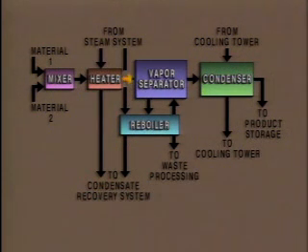From the heater, the heated liquid flows to a vapor separator. In the vapor separator, some of the components of the hot mixture flash to vapor. The other components remain in the liquid state. This flow path represents liquid in the bottom of the separator that is sent to a reboiler. In the reboiler, part of the liquid is vaporized. The vapor from the reboiler is returned to the vapor separator. The waste product that's not vaporized in the reboiler is sent on to another system for processing.